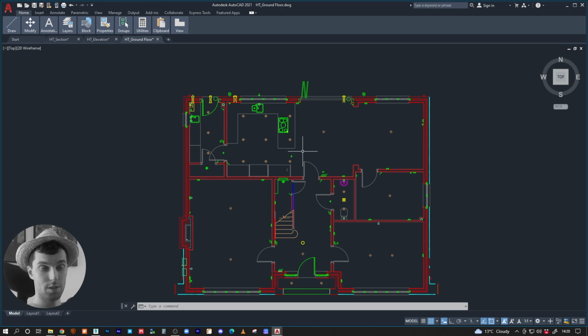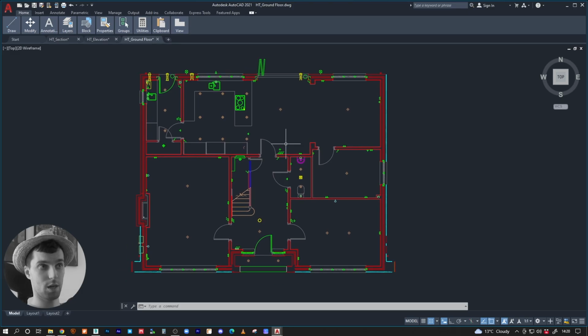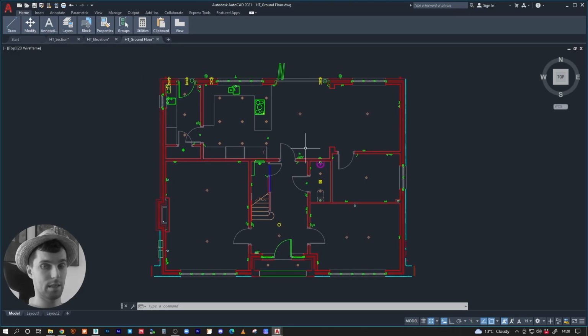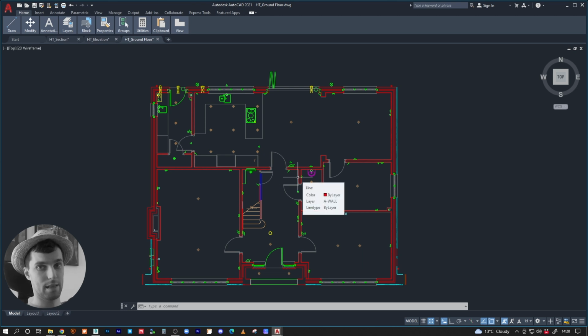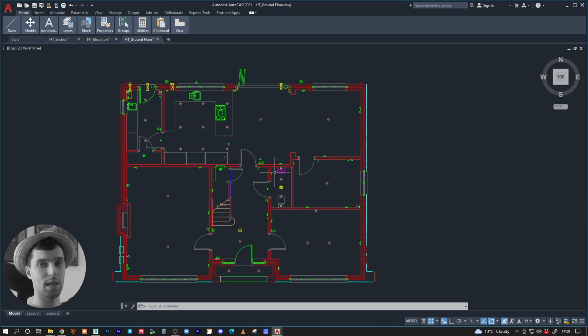When we're importing this drawing into Max in the next lesson, I'm going to show you guys how to properly clean it and finalize it, attach all the splines and delete all the rest of the crap that you imported into Max. But basically your job is to clean the drawing enough so you wouldn't need to import all the crap that you have in the CAD, because sometimes you can have a lot of stuff in there, right? So you don't really want to make your scene that heavy. You want to keep the CAD plans as light as possible when importing into 3ds Max.